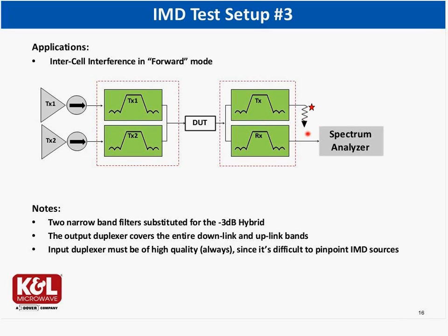Past experience shows that sometimes you do, sometimes you don't. It depends on what it is you're trying to measure, and on how much different the IMD generated here will be from the IMD generated by the device under test. There's really not a 100% need to do that here.